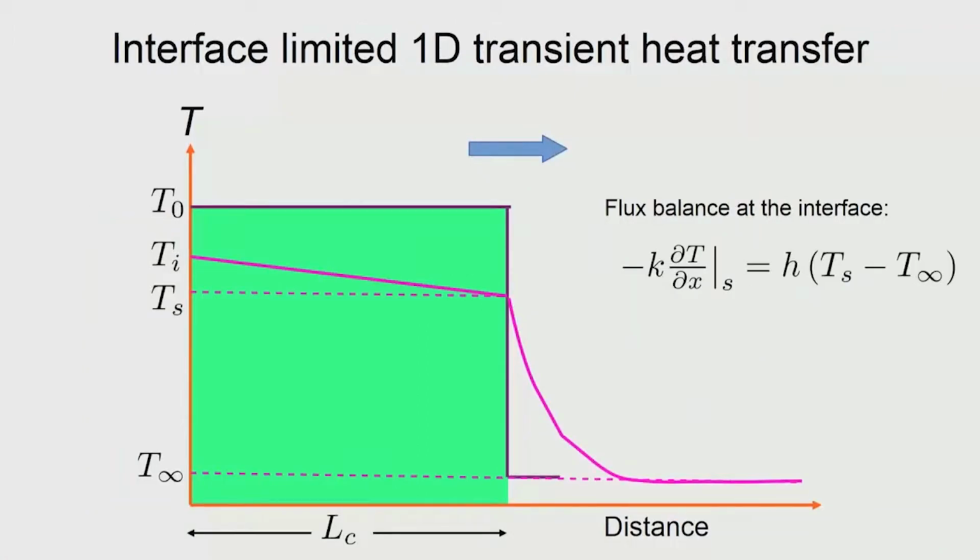So, as we have discussed, the temperature gradients are very small inside the bulk. So, that is why we see that Ti minus Ts is a small number, and therefore inside the bulk you have got a small gradient, and the heat loss is in this direction, and you could see that whatever heat flux is arriving at the interface should leave. So, what comes here should leave. So, they both must be equal for a flux balance, because there is nothing special that is happening at the